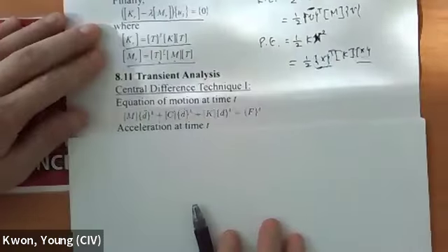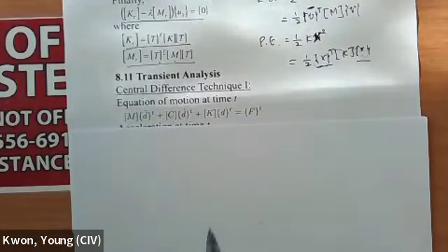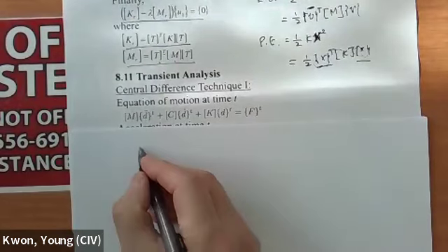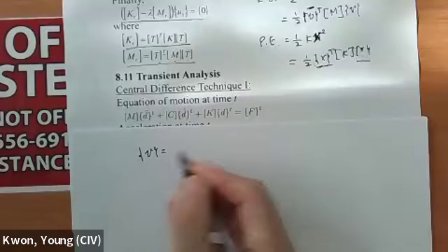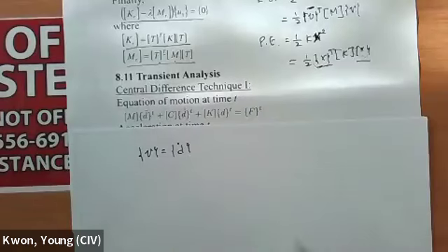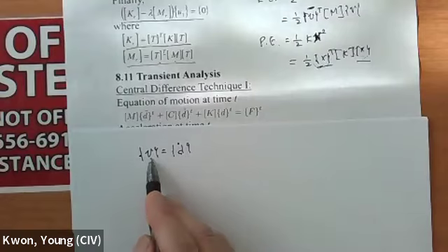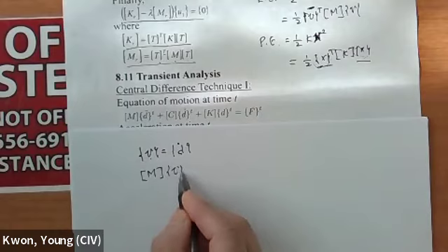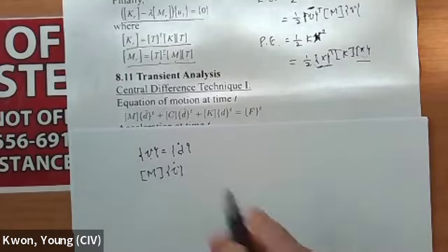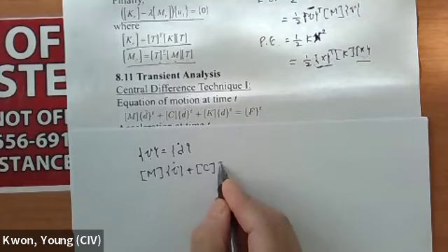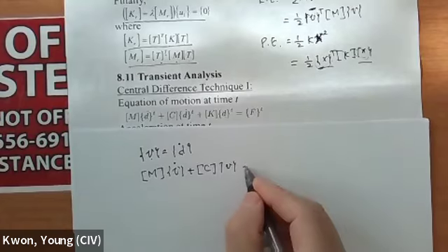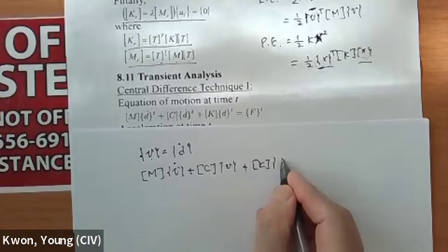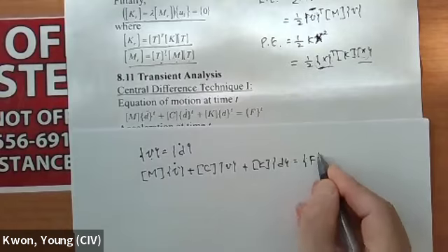You can transform this equation a little different way. So in other words, I define v as d dot. Like this displacement d, v is velocity, right? Then this equation is M v dot plus C v plus K d is F, right?